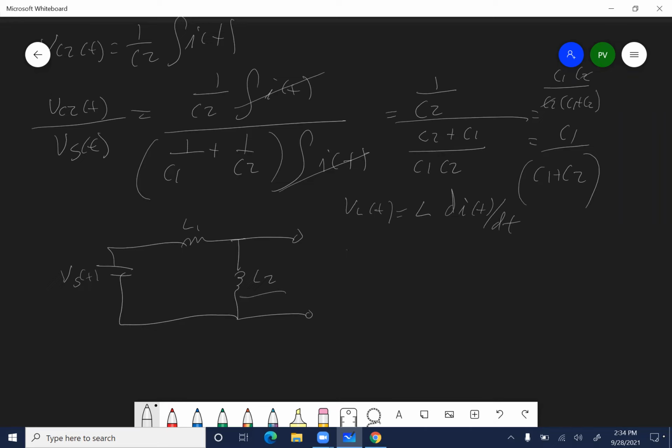Let's take a peek. The first thing we're going to do is write an equation for VL1, and we're going to do the same thing for L2. And again, we're looking at KVL. We're looking at Thevenin, the equivalence of the circuit, to make sure that we get our correct values. So what we're saying is the current through here is the same, because the current is equal to 0 because it's open circuited. There's no current going out of the terminals. Everything is staying inside of the terminals.